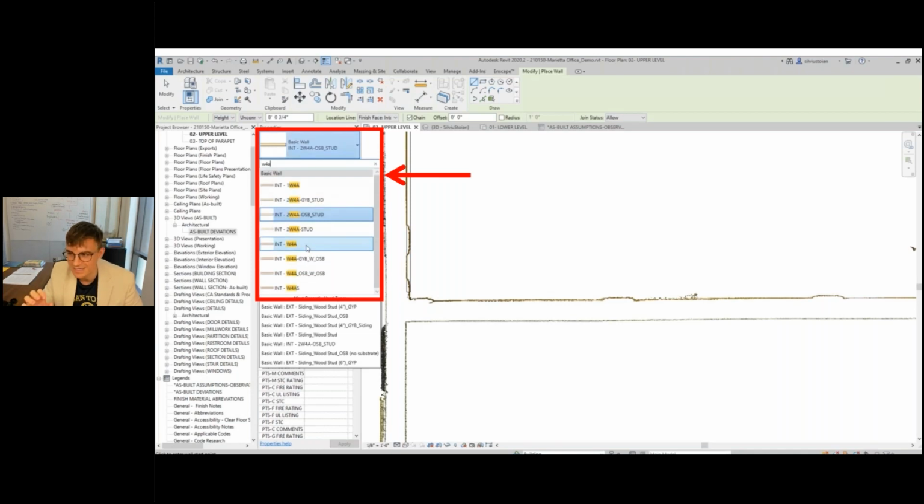And when trying to reconcile the specifications in the contract with the information in the point cloud, do not overstate the level of detail in the model. Delivering true LOD 300, you may need access to information that is actually hidden beneath the surfaces that you scanned. Making assumptions can get you into trouble. And when making these kinds of educated guesses, just make sure you're communicating with the client and saying, in some cases, it's an LOD 200 plus.